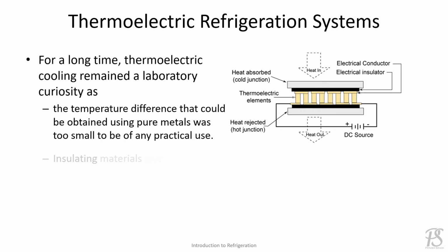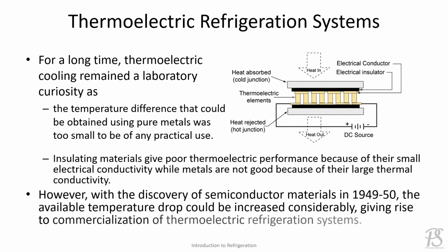For a long time, thermoelectric cooling remained a laboratory curiosity as the temperature difference that could be obtained using pure metals was too small to be of any practical use. Also, insulating materials give poor thermoelectric performance because of their small electrical conductivity, while metals are not good because of their large thermal conductivity. However, with the discovery of semiconductor materials in 1949-1950, the available temperature drop could be increased considerably, giving rise to commercialization of thermoelectric refrigeration system.